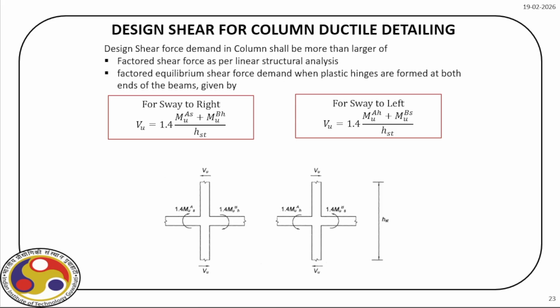So, design shear for column ductile detailing. Again, this is important. Recall, for the beam we have already discussed. Similarly, for the column also, the same frame will sway to right or sway to left, and accordingly we have to find out the shear force acting on the column. So the design shear force demand in the column shall be more than the larger of these.